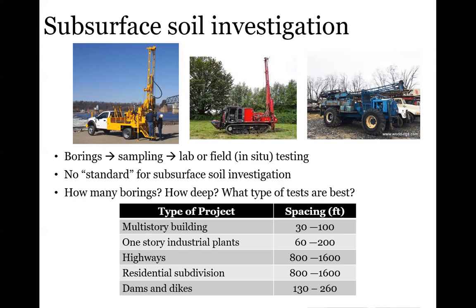So we need to ensure that the actual data collection is of high quality too. So the soil samples that we're collecting, the boring, the investigation techniques aren't including any additional errors just to stack on top of that. So these are some of the guidelines here, these spacing, but of course it's up to the geotechnical engineer or the client to really define how much testing is performed at a site.